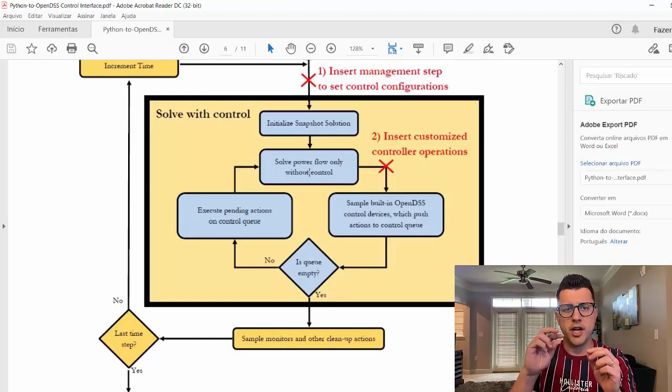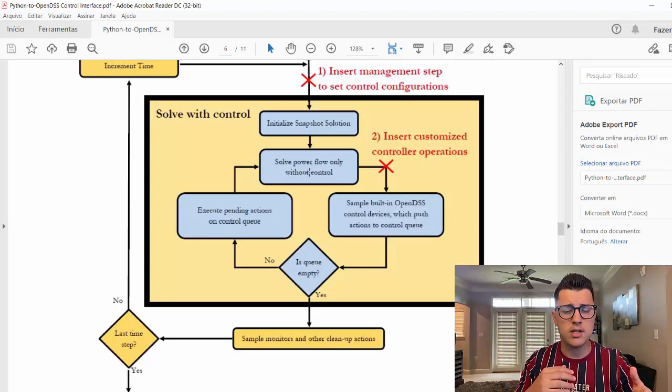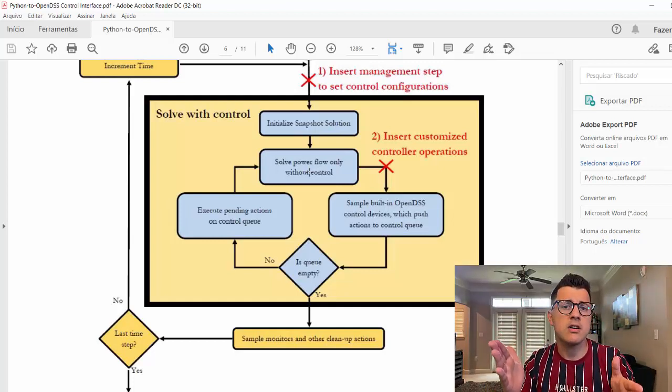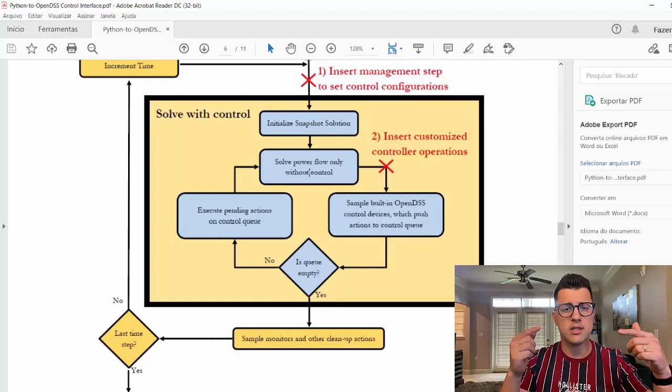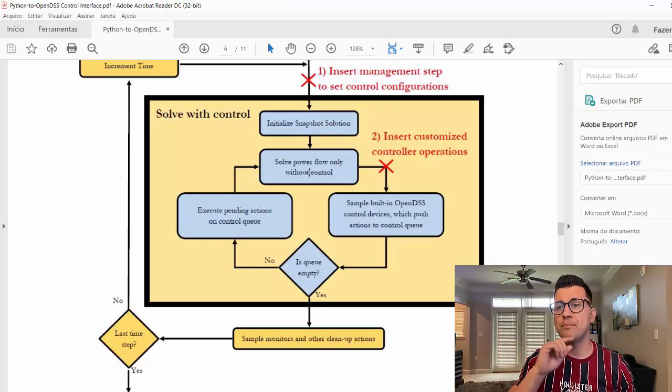We change the voltage, we change the compensation current of the generators and loads, then we perform a power flow, and we get a new set of voltages. With this new set of voltages, we then change the currents, and you do that until the voltages between two iterations are so close to each other that you say, well, that's the voltage that makes sense. Okay, cool. So let's say you take 4 iterations to converge.